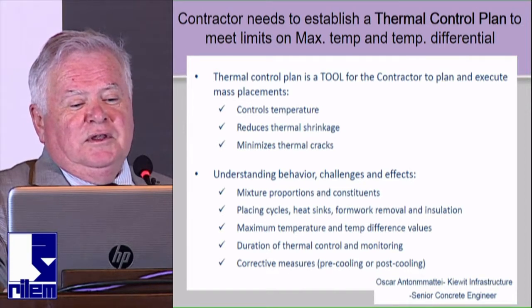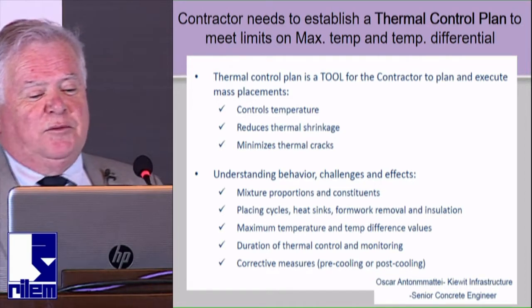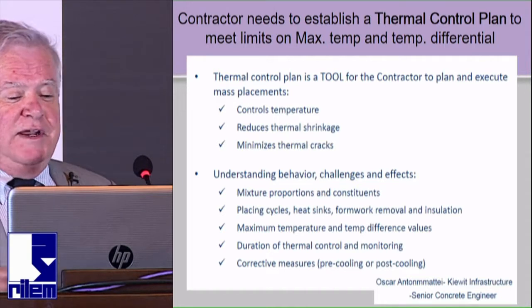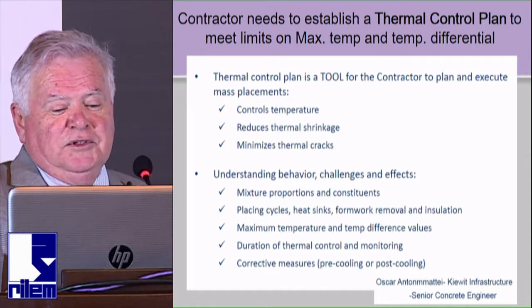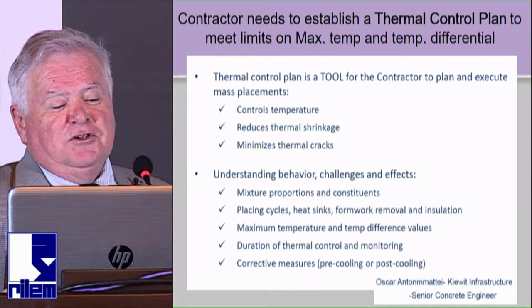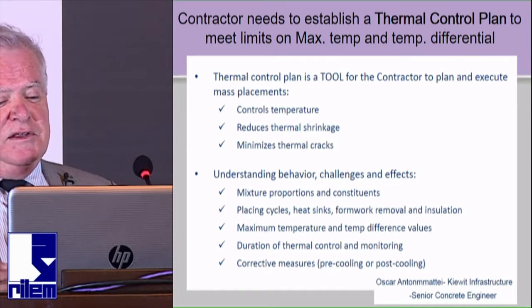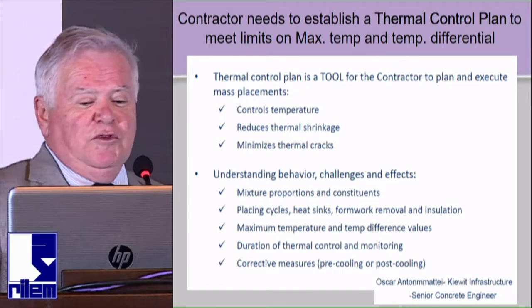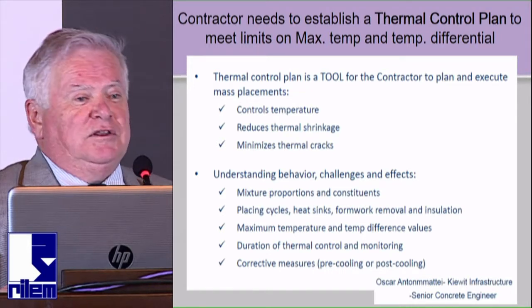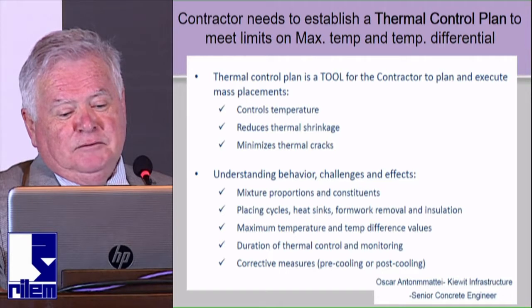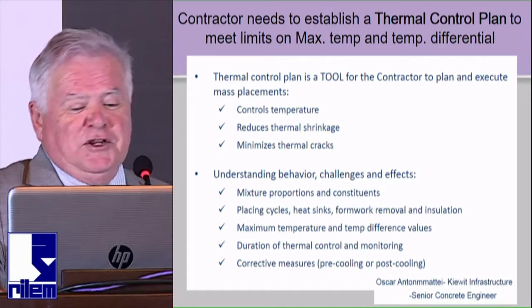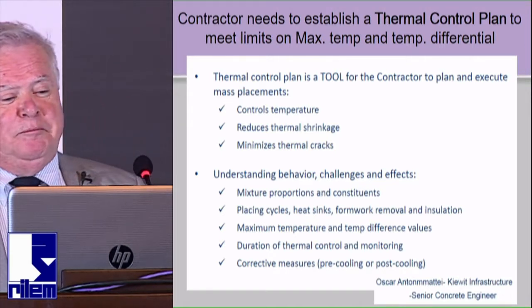So they want to control the placing temperature, the maximum temperature. They want to control the thermal gradient, and there's a bunch of things they do, not just the mix design, but how they place the concrete, placing sequences, heat removal, form removal, insulation on the forms, and duration of that protective measures to try and minimize the cracking.